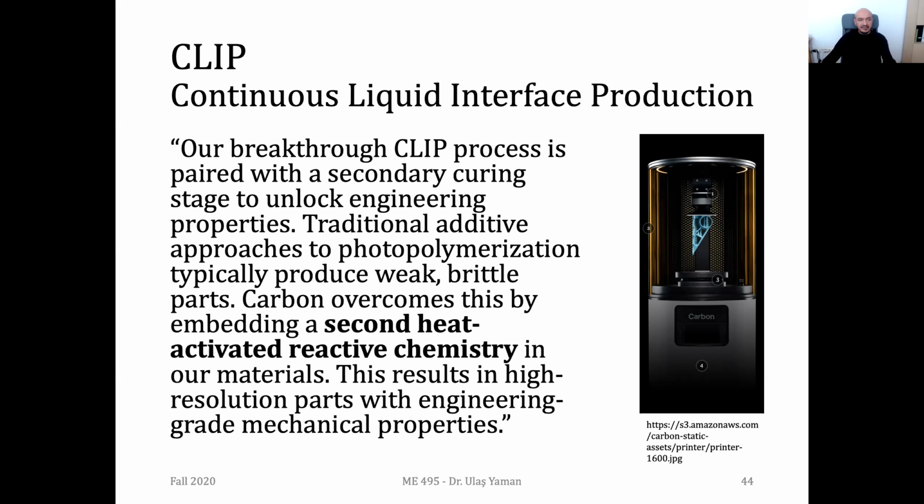Now in this special type of photopolymerization process, we will be focusing on a patented technology called continuous liquid interface production, abbreviated as CLIP. This company is called Carbon 3D, and their fundamentals are very similar to the DLP technology or mass projection stereolithography, but the difference is that they have a secondary chemical reaction.